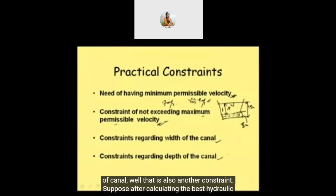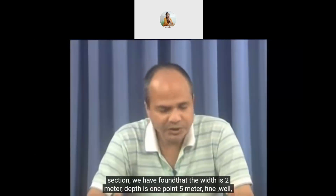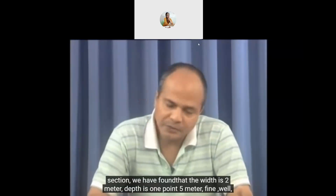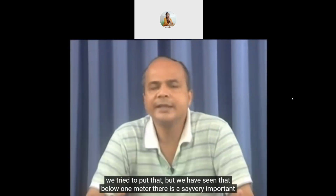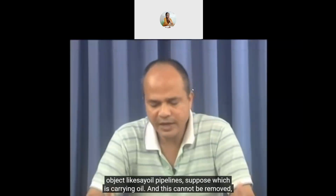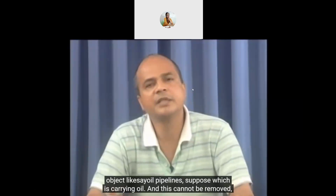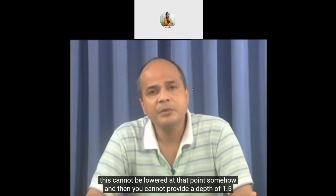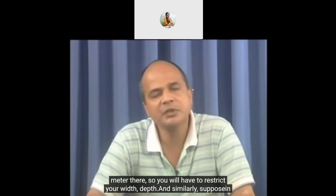Suppose after calculating the best hydraulic section, we have found that the width is 2 meter, depth is 1.5 meter. Fine. We tried to put that, but we have seen that below 1 meter there is a very important object like, say, an oil pipeline, which is carrying oil, and this cannot be removed or lowered at that point somehow. And then you cannot provide a depth of 1.5 meter there. So you'll have to restrict your width and depth.